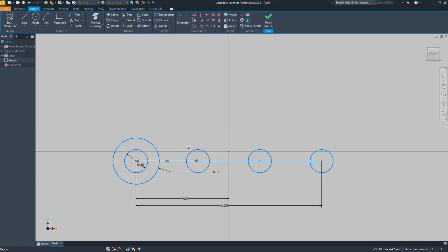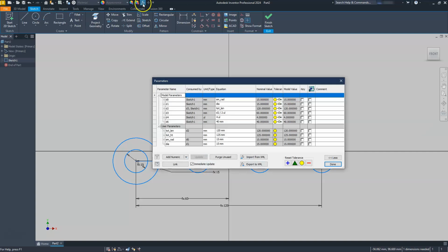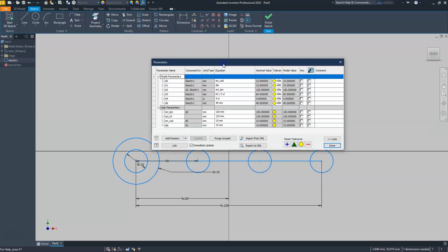And then we're going to go back and take a look at our parameters and see if there's any way we can put a little bit of intelligence into this. So I'm going to go up here to my function. And you can see here that I have 4 units, and then I have the distance between them. So all I'm saying is that I should be able to take this number here and divide it by my total length, and that should give me, ideally, this one. That's telling me the space in between them. It's not going to give me 4, but it's going to give me whatever that number is minus 1, and it will create that.